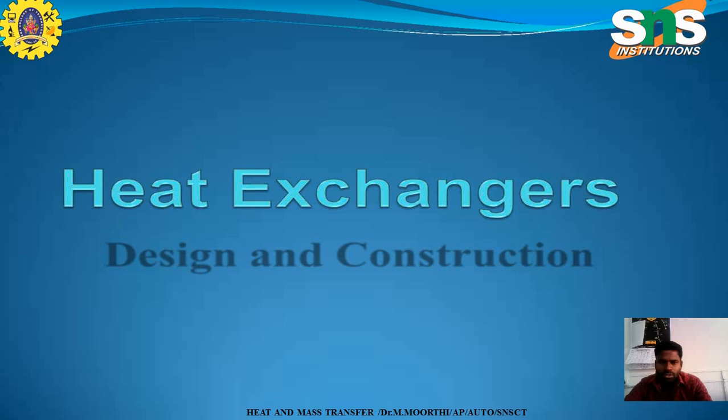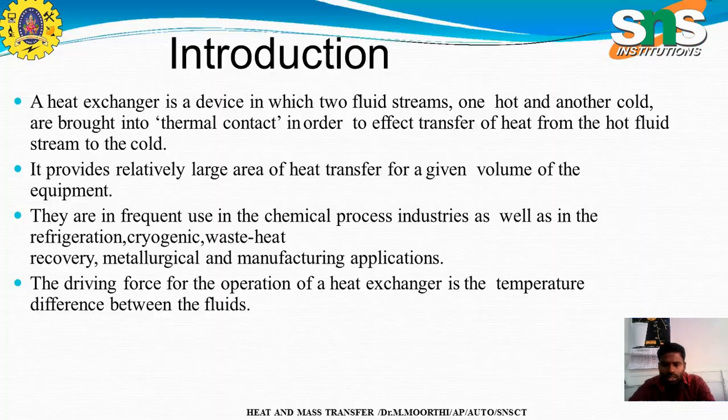If you want heat transfer from a cooler body to a hotter body, you can make that heat transfer happen artificially. So first we should know what a heat exchanger is. A heat exchanger is a device in which two fluid streams, the hot and cold mediums, are brought into thermal contact in order to effect transfer of heat from the hot fluid to the cold medium. So this is generally a heat transfer,